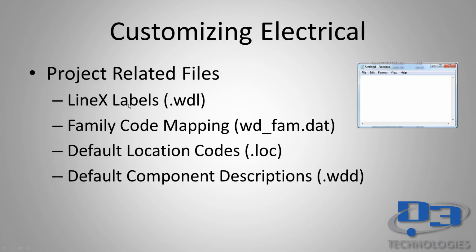This is a text file that we can create that will map our line values in our project descriptions to a more descriptive text, such as line 1 equals engineer, line 2 equals project, line 3 equals project location, etc. This will add some efficiency and definitely give every user the clarity of what exactly this attribute or this line value is going to do, whether that is going to populate an attribute and be utilized in a report.